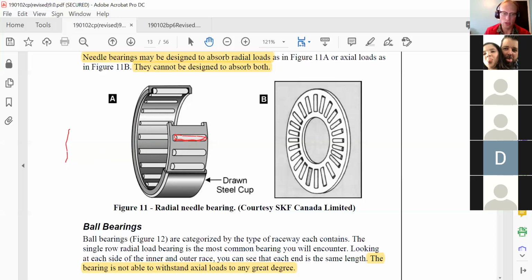Yeah, exactly. And not all U-joints are like this. You'd never be able to tell by looking at it. You'd have to take a really precise measuring tool and measure the rollers to actually tell. It's a very, very fine taper. Does that mean the trunnion is also tapered as well? It isn't tapered as far as I know. I've never heard that they design it like that. Now, could it be? Absolutely. This isn't something that's clean across the board. This is just with some U-joints. And like I said, you'd never know to look at it. It's very, very minute.